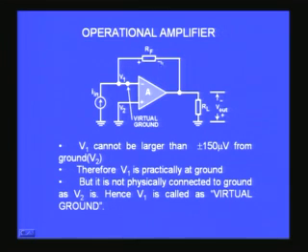So, now what is the voltage at the output? The voltage at the output is the voltage that you measure by using a voltmeter between the output point and the ground, but the output point and this point are also equal because this point is a virtual ground. So, if you measure by a voltmeter from this point to the ground, it is the same as measuring this point with reference to this point. Therefore, the voltage here is nothing but the I in flowing through RF, which is a feedback resistor. So, that is the voltage that you will get here, and it is negative.